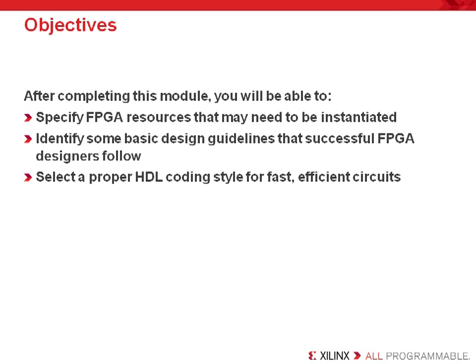Now, this flow allows users to work around limitations all synthesis tools have with regards to automatically inferring the best FPGA resources. The bottom line is that all the high-end synthesis tools available for the FPGA industry usually do not allow inference of all the best FPGA resources. That is usually the latest and greatest, like the DSP slice and block RAM resources. Now, synthesis tools may allow some inference of these resources. There are plenty of exceptions, but usually only primary applications are inferable.